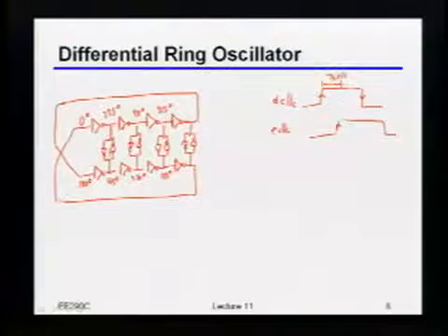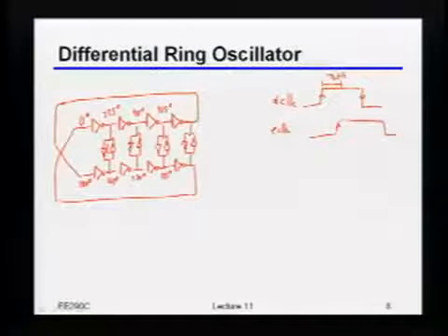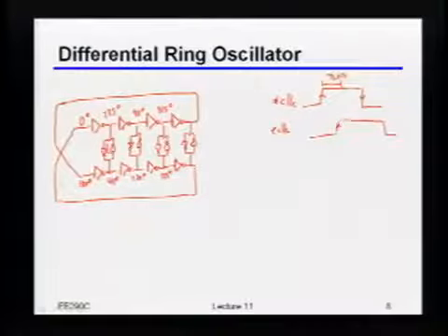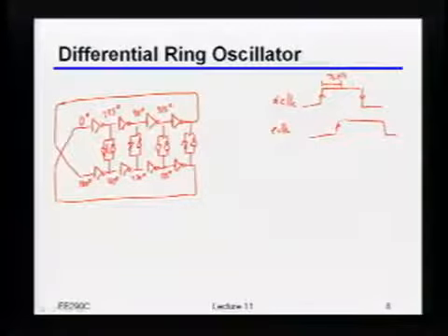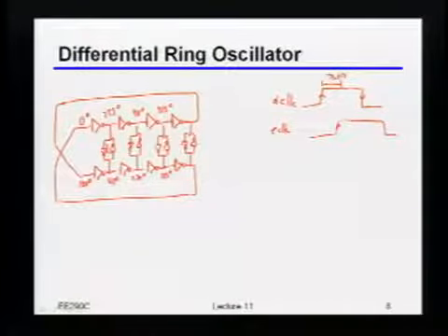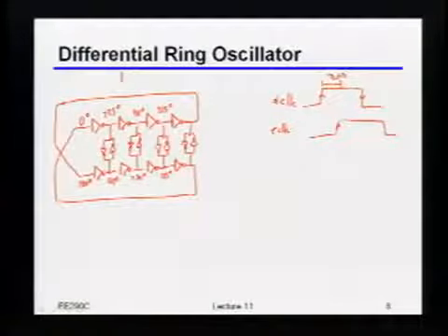So when I add these cross-coupled inverters like this, is that a good thing or a bad thing from the standpoint of speed, power, etc.? It reduces your frequency, right? So for the same clock frequency, you're going to have to raise the power supply voltage, so you have to spend more power, not to mention that you have crowbar currents because they're fighting each other.